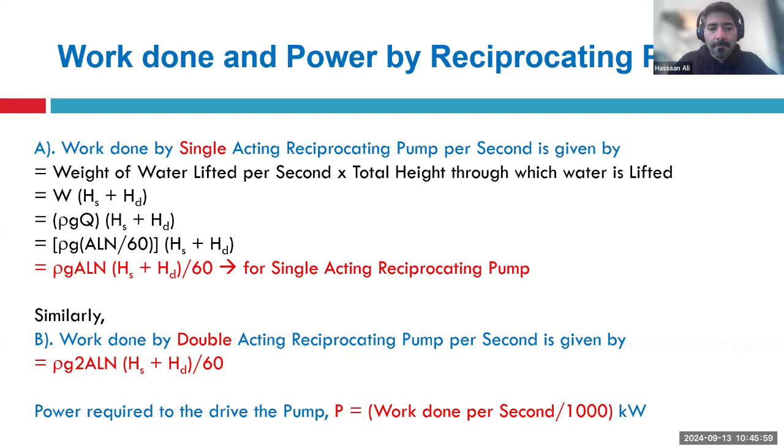The other factor you need to consider is the head of the pump: how much vertical distance it needs to cover, how much is the suction height, and how much is the discharge height. So all of these factors help you spec out and select a proper pump.